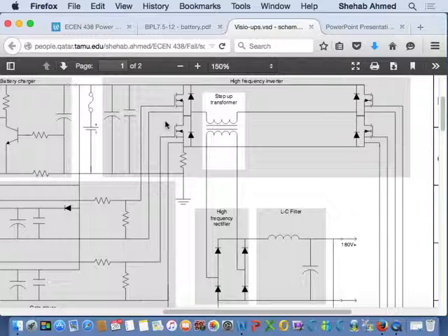But for now, because they rely on this alternating magnetic field, I have to put an AC voltage at the input of the transformer to get an AC voltage at the output, and then I can rectify that. That's exactly what I'm doing. So I'm taking the DC voltage and I'm chopping it up. So I'm doing a DC to AC conversion. DC to high frequency AC conversion.